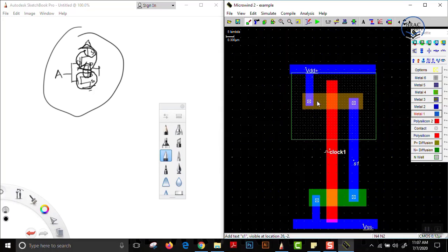Another thing is required. What is it? See, this is a P-type diffusion layer connected to the VDD, and this is an N well. Since the P layer is connected to VDD and there is a PN junction here, there is a forward bias across the PN junction because the potential of the P side is greater than the potential of the N side. Because of this forward bias, there is leakage current and all sorts of current which will give us erroneous output.